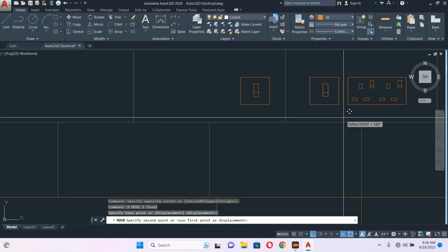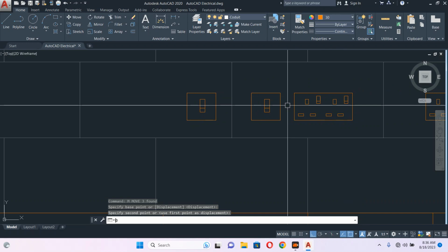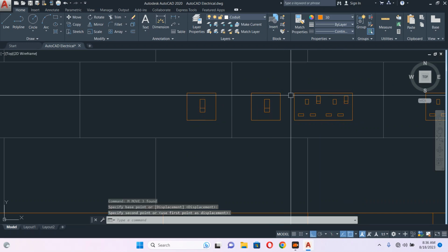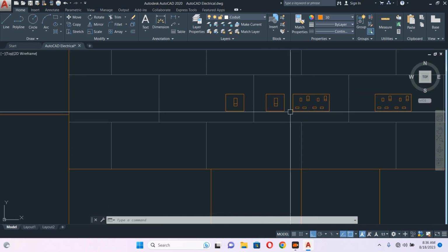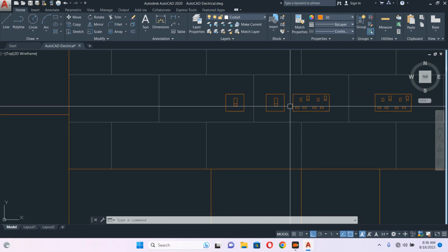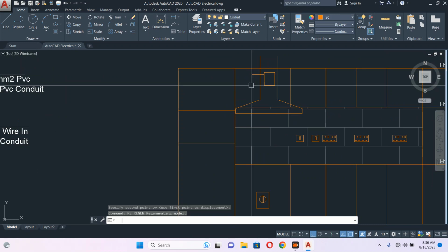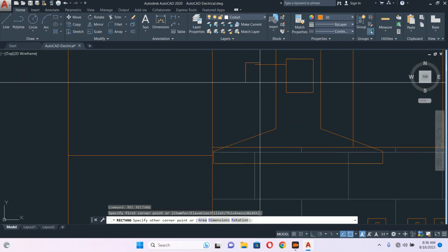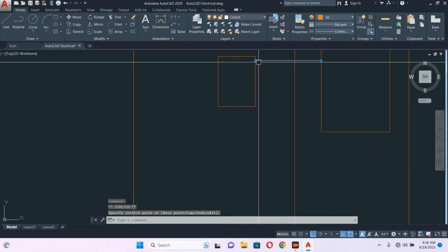Okay, another thing I want to tell you, this gap should be 50. This gap between the outlets should be 50. If there is no space, you can follow 40, 30, no problem, but generally keep 50. So this is the hood. We will have one flex outlet here to connect this fan wire. Okay, flex outlet here like this.